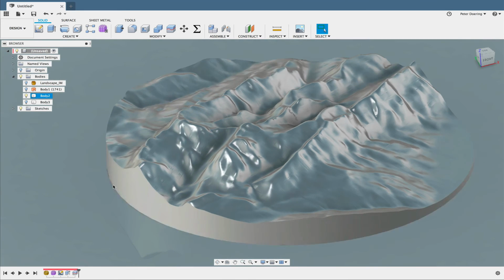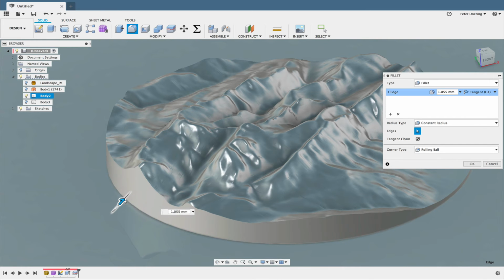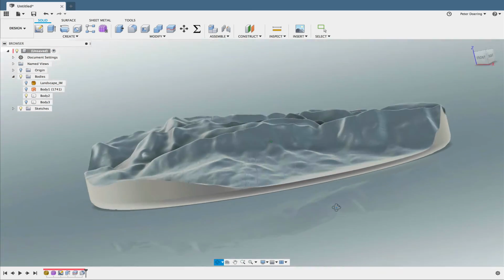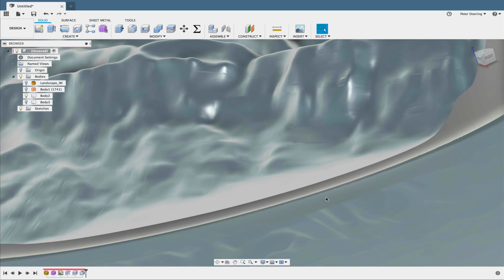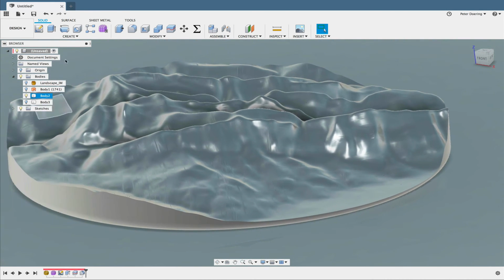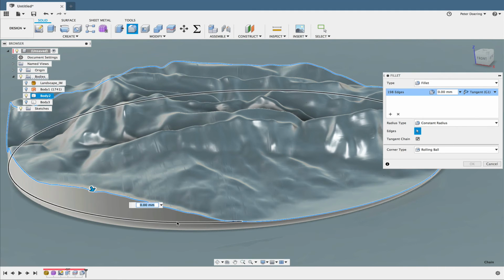So there it is, there's my disk. Then I applied a little fillet here. And well, I also applied a fillet to this edge here. But let's talk about that for a moment. That isn't so trivial, because there's a good chance that if you apply a fillet too large, then Fusion 360 will not do it. So it applied a 0.2 millimeter fillet.